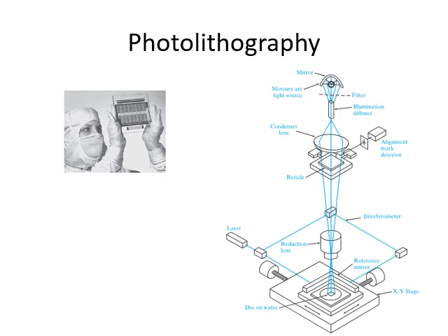Coming to today's topic of photolithography, in the steps of fabrication, you have seen that the photoresist is applied, then a mask is used, and UV radiations are incident through the mask on the photoresist. That entire process is called photolithography.